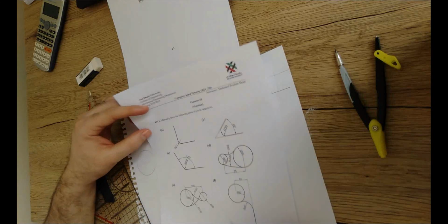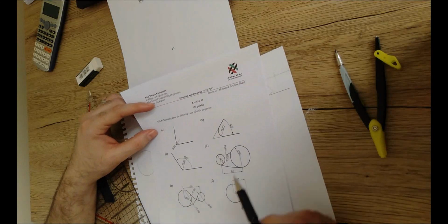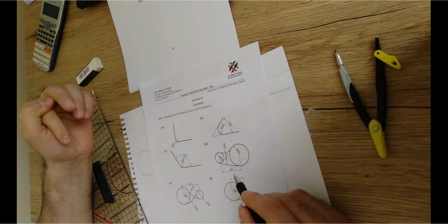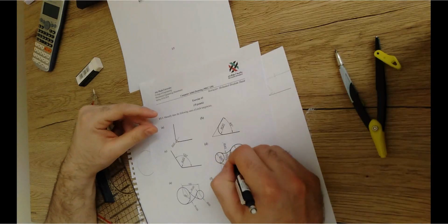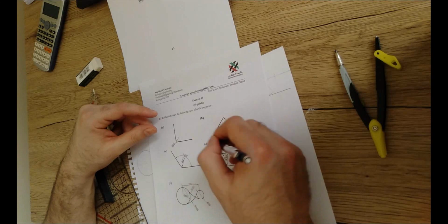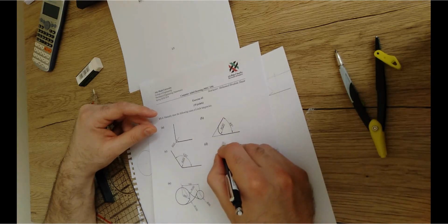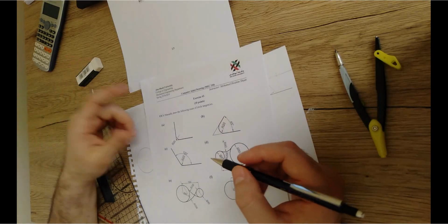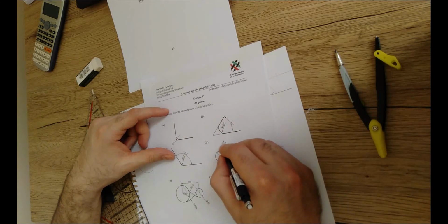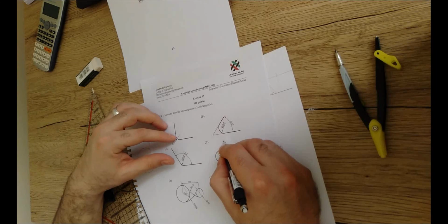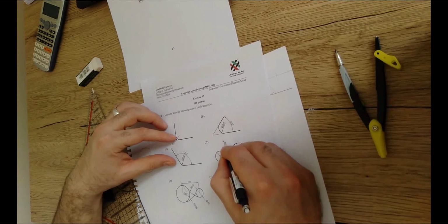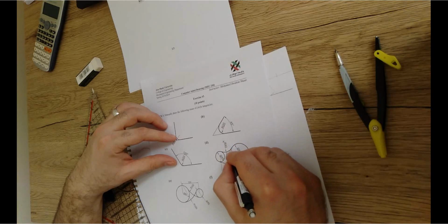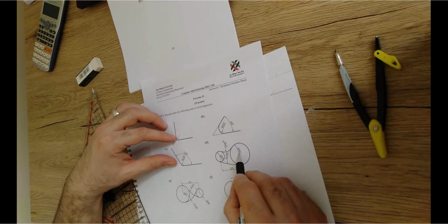Now we have to work over the tangencies here. We do have, let us start with the small curve, which is the R40. As we practiced before, as I explained, you just ask yourself, simply, we have to locate the center point of this curve. So you have to ask yourself where it should be the center point of this curve. It should be located somewhere here. Then, this is the first question that you're gonna ask. Then the second question is, how long is the distance from the center that we don't know yet to the center of this circle? It's gonna be the 40 plus the 40. It means that it's gonna be the sum of the radius of the first curve plus the sum of the radius of the second curve.